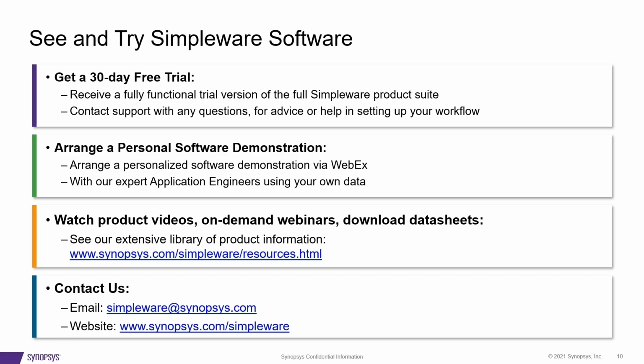Yeah, for instance, yes, we can use, as we said, different types of elements, and for tissue, again, yes. Since the subject of this study was the deployment and the stent mechanical behavior or performance evaluation, we didn't consider a specific mesh or material model for tissue, but for sure we can add this part for the next study. And we do currently work on such a project with somebody we cannot talk about, but it's definitely something that people are getting more interested in.